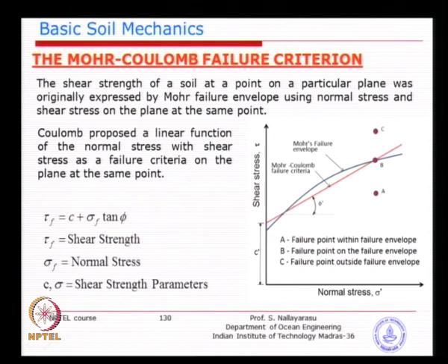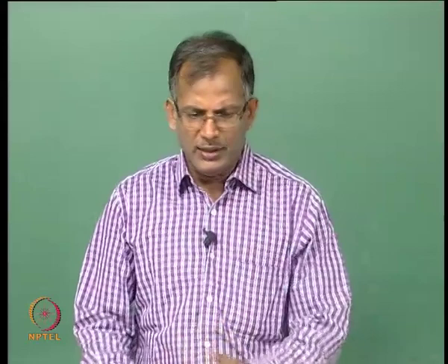In case of 3-dimensional stresses, it will be a complex surface which will be difficult to derive. So, that is why this simplified Mohr-Coulomb criterion is commonly used in most of our foundation design because of its simplicity, and we will be using that throughout the course, which will be very useful.